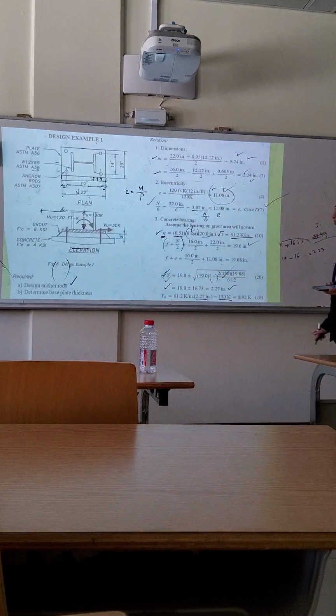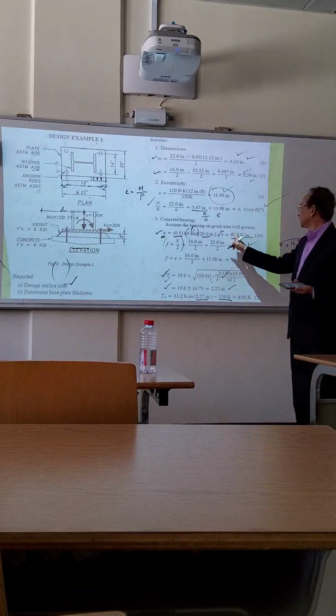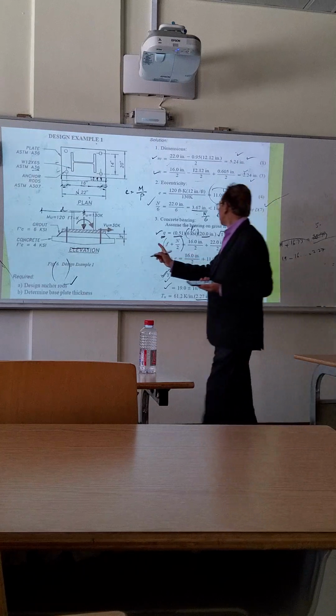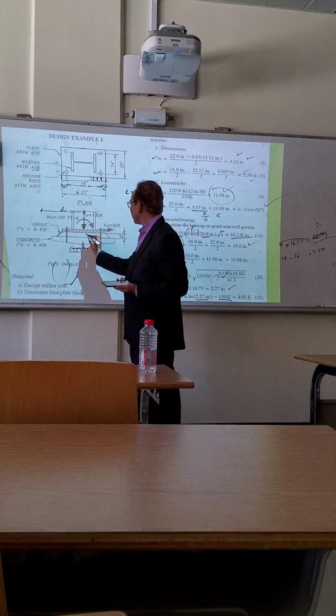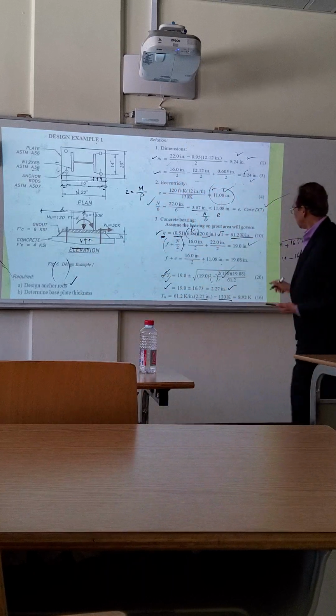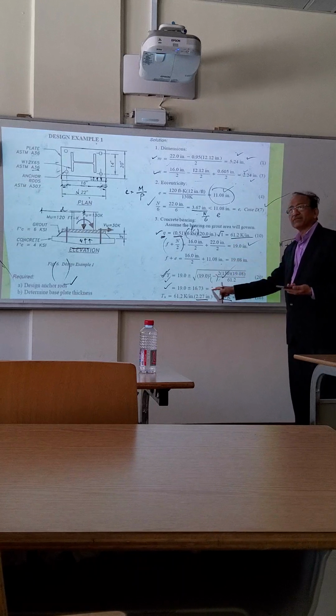And you will get this 16.2 from here. This is your pressure, 61, that is pressure of concrete. That pressure of concrete is in this direction. This is your Q. And for how much length? The length which is under compression is only 2.27.